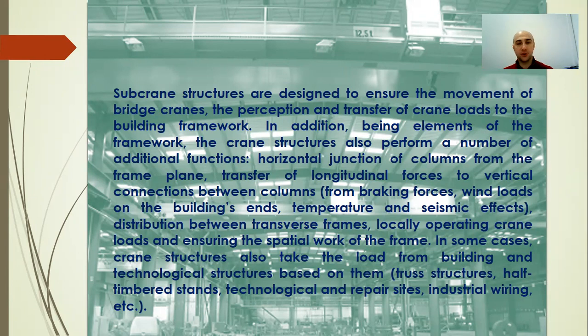With the column pitch, so the column step between two columns, of 12 meters, the subcrane beam length will be about 11,950 millimeters, the height 1,400, 1,600 and 2,000 millimeters, and the shelf width 650 and 750 millimeters.